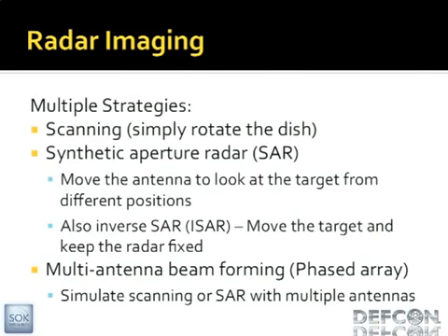There's something called synthetic aperture radar, which basically means you can get better resolution if you have a bigger dish. But the problem is that bigger dishes are more directional, so that's the advantage. With synthetic aperture radar, you're taking coherent measurements of the signal at different places, and you're trying to simulate having a larger dish. The reason you would do that is so that you can get a finer resolution of space. If you just point it in one direction, the beam widths on these things are like 40 degrees or something, so you couldn't see anything out there.